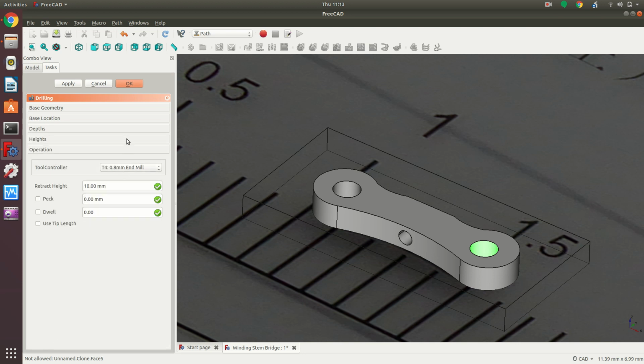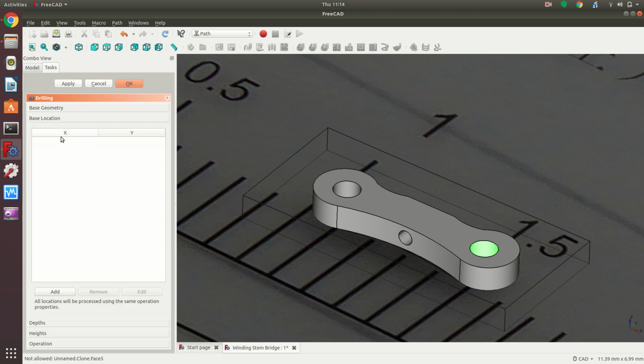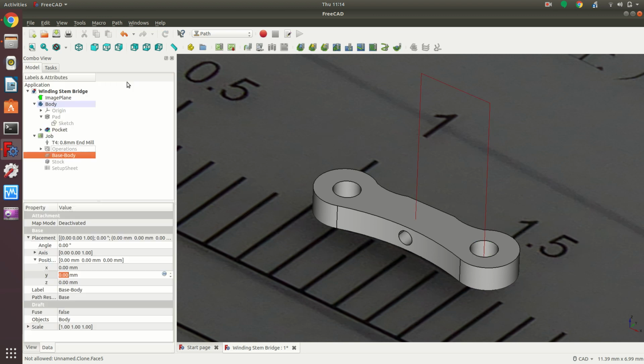Okay, retract height, that's also important. Before the machine drills, it'll go above the workpiece by the retract height and then start drilling. As we've got a really, really slow feed, you'd have to wait minutes and minutes till it goes from 10 millimeter to drilling the hole. We don't need that. 0.2 mil is absolutely fine. That's just the height from the zero position as it goes across. Exactly. Yeah. So that's fine. All the rest we have, we say okay.